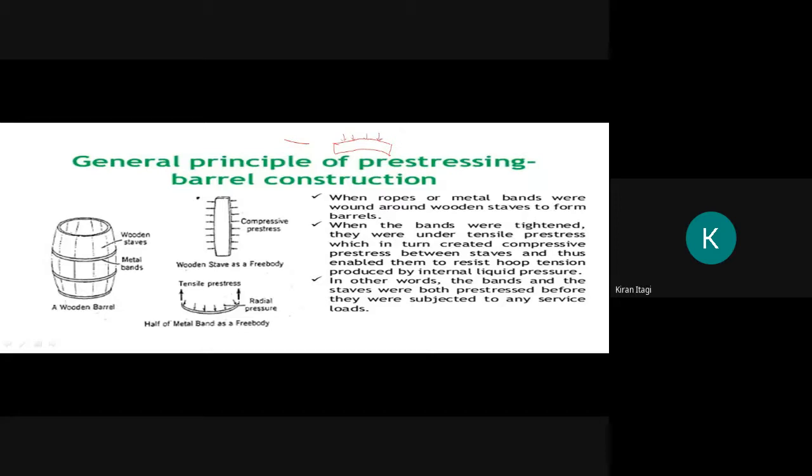After application of the load, it will become like this. But our RCC was initially like this, then it sagged after application of the load. But in our pre-stress, initially we provide some tension. When load acts upon it, it counteracts. Remember the word, it counteracts and it keeps the beam in this way.